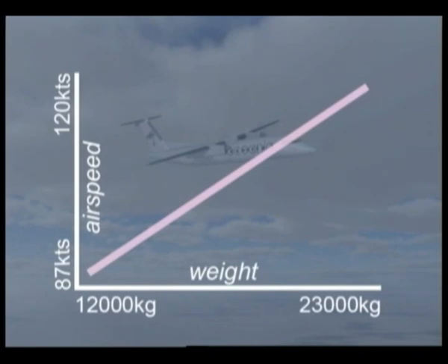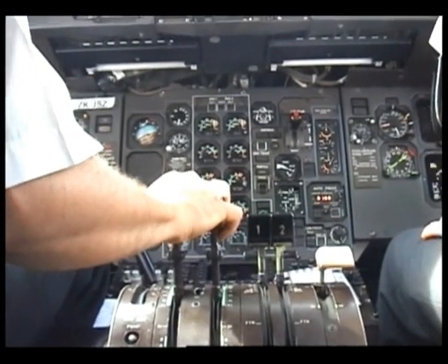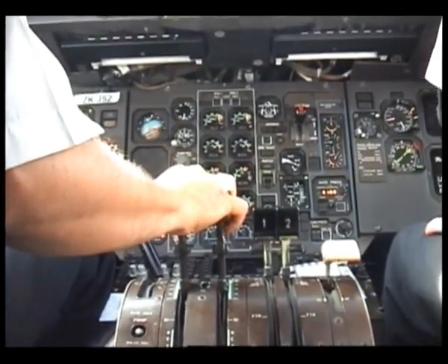To be technical, it may be said that the stall speed varies according to the loading on the wings or the requirement for lift. If flying slow has its problems, so also has high speed.